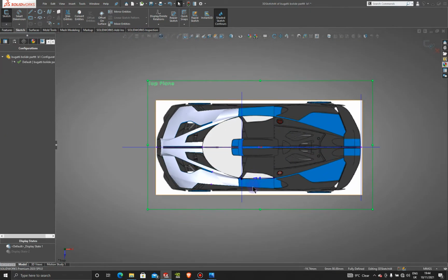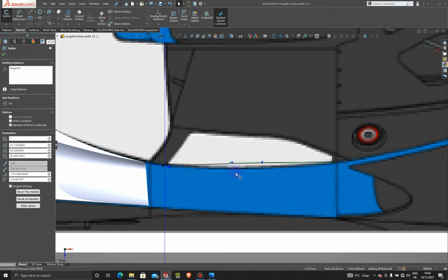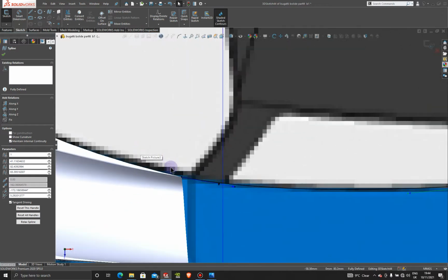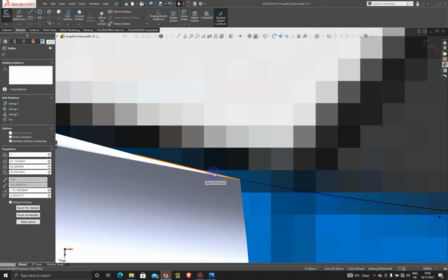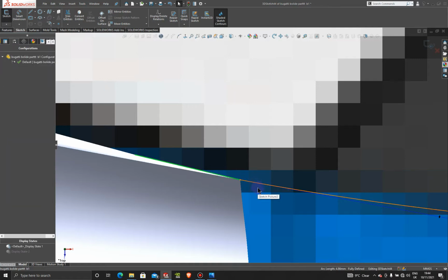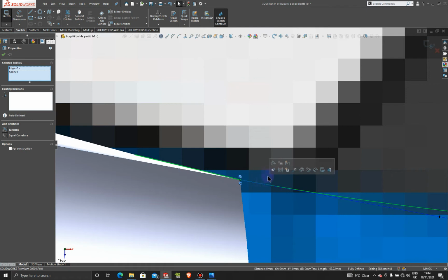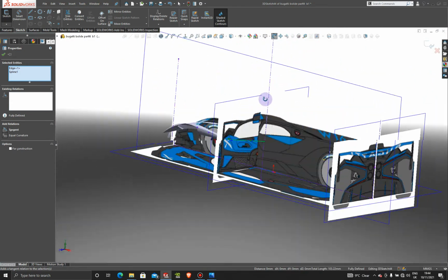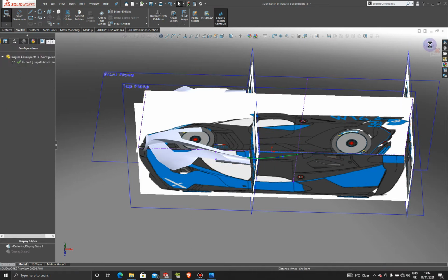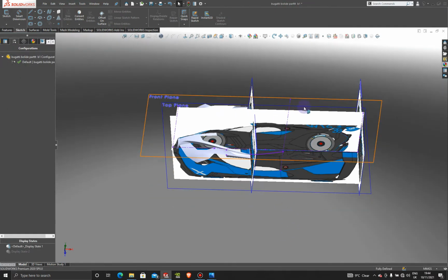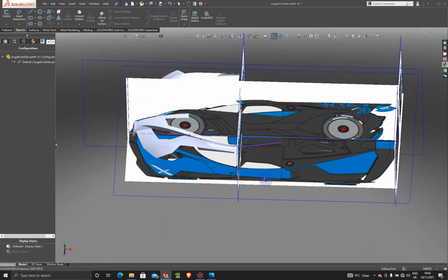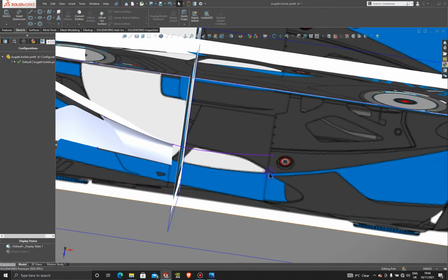And let's jump to the top here. Of course, we want to make that nice and curvy. Over here, we can try and add a tangency with this line here. Hold Control, and press this line and tangency. We don't need to do that because it's already tangent. Alright, so that looks good. So we got our first line. Exit the sketch. Alright, then now we can hide this construction line so it won't be in the way. That's good. And now let's hide this point as well.